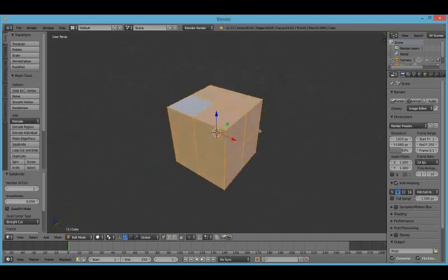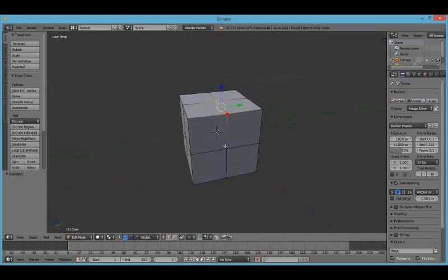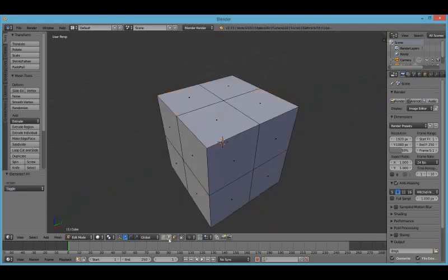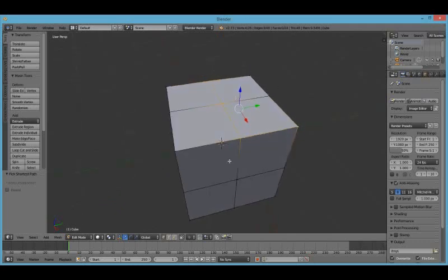So here I'll show you a way to select more than one vertex at once. Just right click one and then hold down Shift and click any manner. You can unselect each one individually in the process that you selected them by pressing CTRL Z. So that's absolutely vital. Another thing that you can do with the Shift, so you can just click with the faces or the lines. Really handy stuff. Another little tidbit here. So you can right click and then hold Control and click at a different point, and it'll do its best to map out every point in between. It's great stuff.